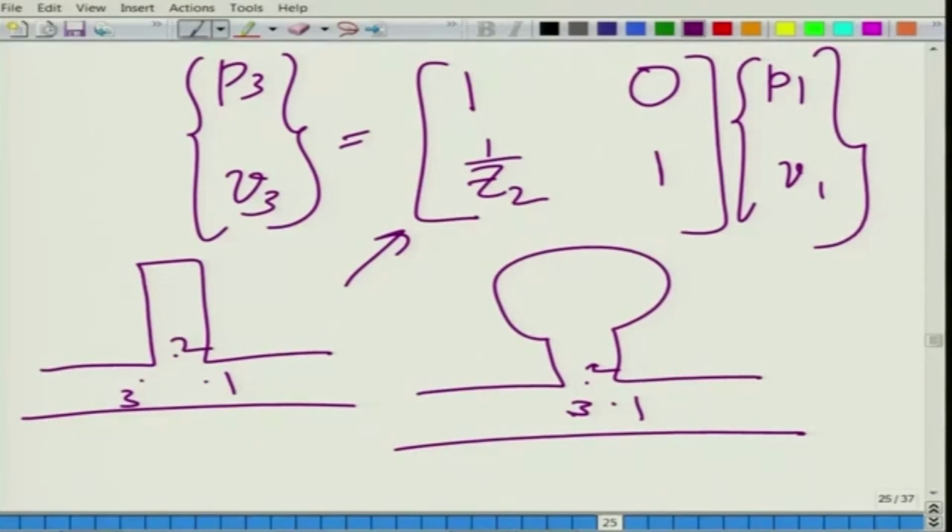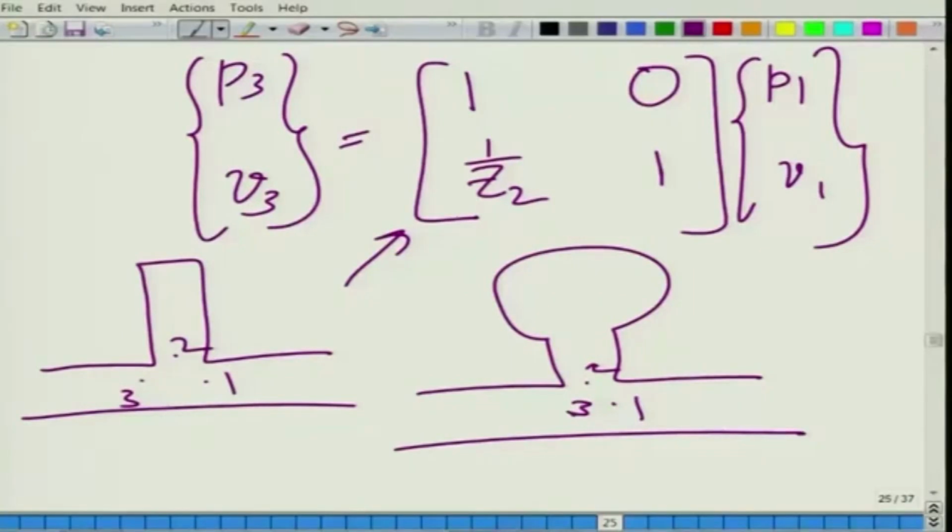First of all, reactance going to 0, impedance being a complex quantity. By setting the reactance or the imaginary part to 0, we can get the resonance frequencies. Of course, you will not just get one, you will get a sequence of resonance frequencies if you consider a planar wave analysis and not just a lumped system analysis. You might have to solve transcendental equations for that, or solve them numerically.